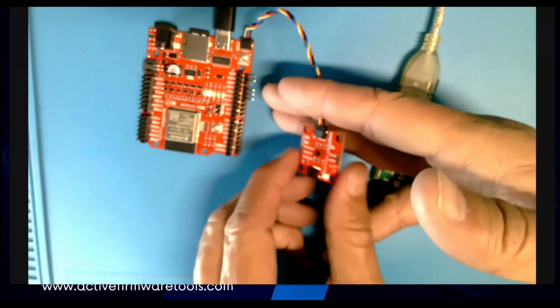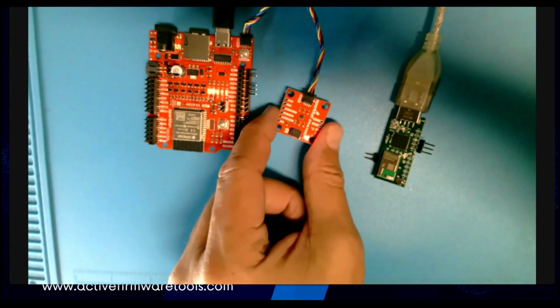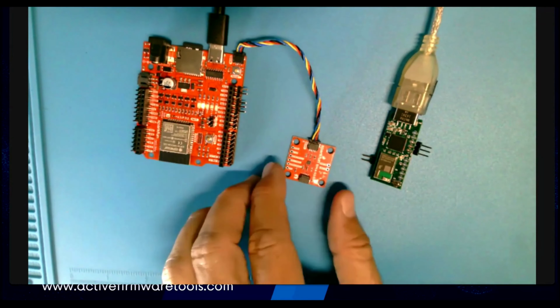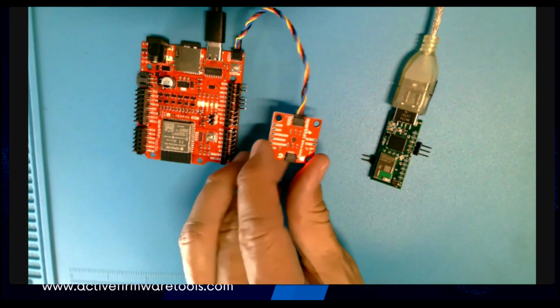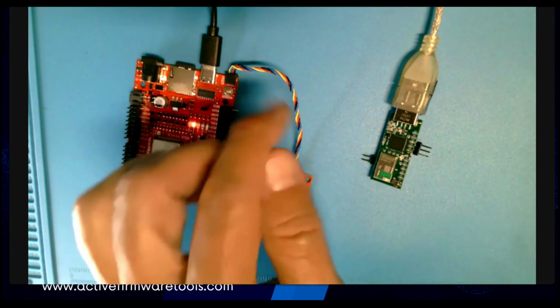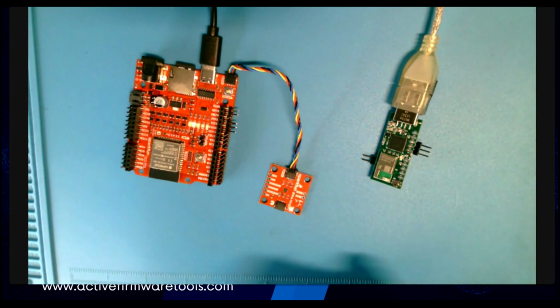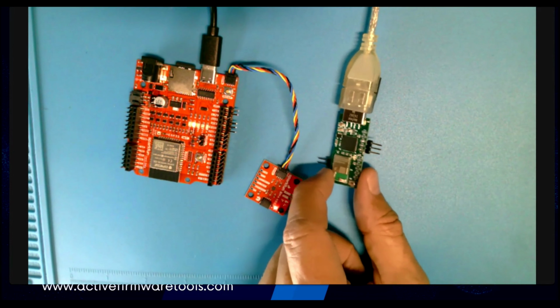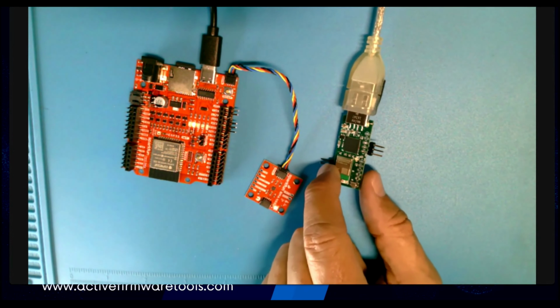It's attached to a BMA 400 accelerometer board. This cable is the I2C bus. It's got the SDA and SCL lines on there. I think it's got a couple other lines as well as ground and power, I believe. The other board we have here is what I'm calling the sensor hub. It is the receiving side of the BLE packets.